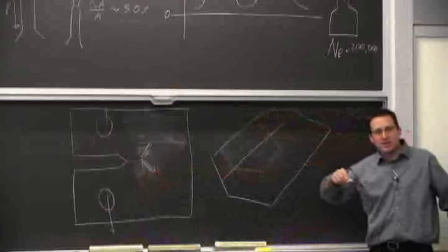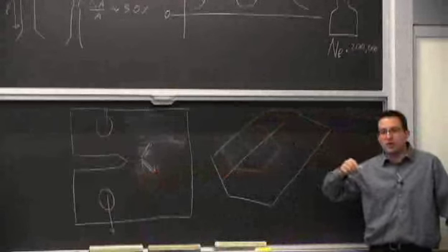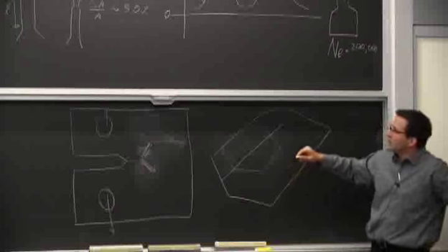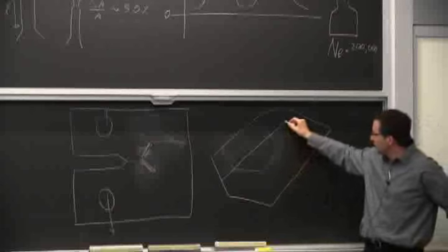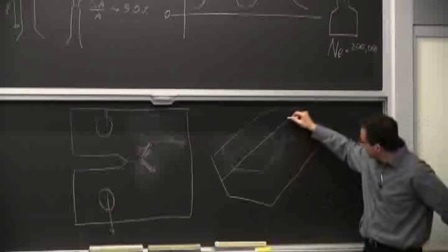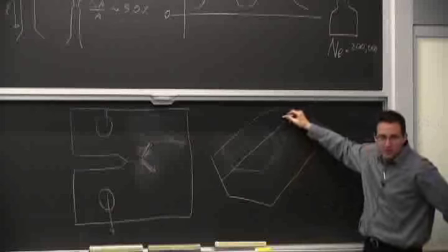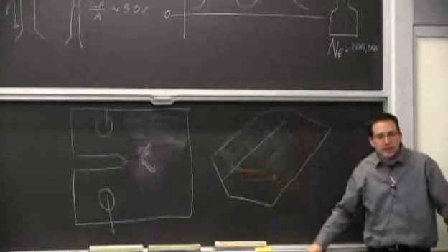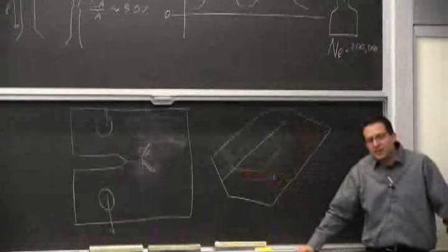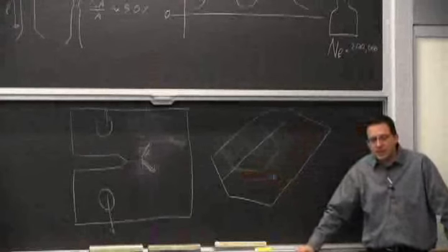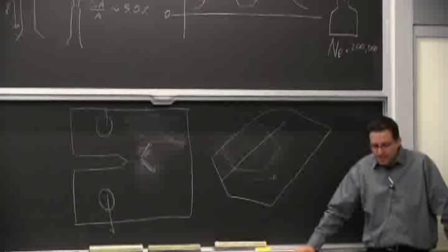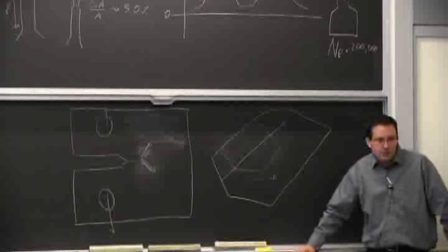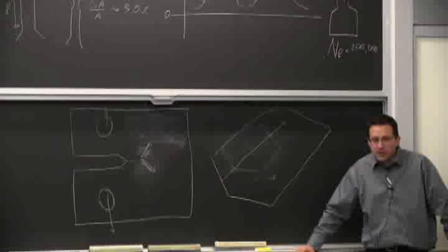So now it has to take a detour with a reduced, what we call the effective or local K. So the stress intensity to grow a crack like this, when the stress is this way, is not quite as big as just to grow it straight out, like we talked about. So that's a little bit what this portion of the slides talk about, that you'll have roughness in your fracture surface, in your crack, that is related to the microstructure.